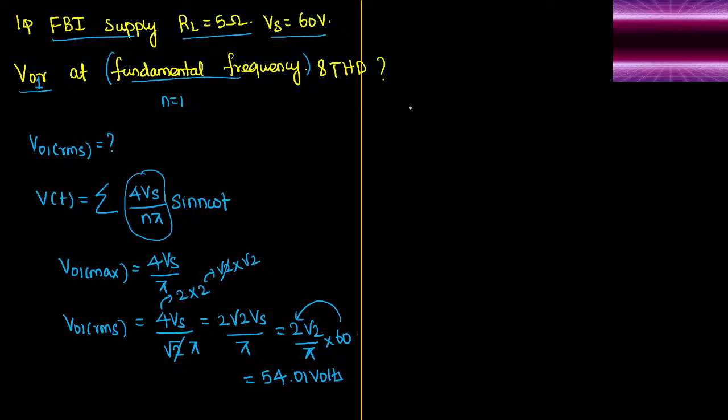I know where you guys got stuck, sir, whether we need to calculate V0 RMS or fundamental. And understand one more thing. Suppose in the same question, I am just asking the output RMS voltage. Anyone? What is the output RMS voltage? R stands for RMS voltage. Just tell me the answer. You guys are writing this formula: sir, V0 RMS equals supply voltage Vs into 2D by pi, sir. Really? Are you guys writing this? This formula is for whom?